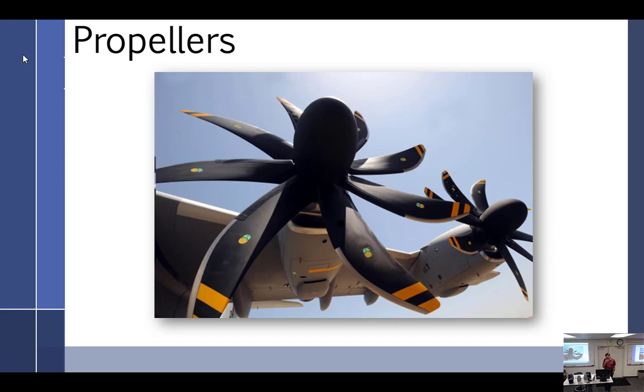So in other words, what he's saying is we have a propeller, and it's just a wing going in a circle. You could vary the angle of that blade, and you'd say you want about a 4-degree angle, and the air is coming this way, and that would make perfect sense, wouldn't it? But then if I take one step forward while I'm doing that, I just changed that wind coming from this way to this way. And that changed the entire angle.